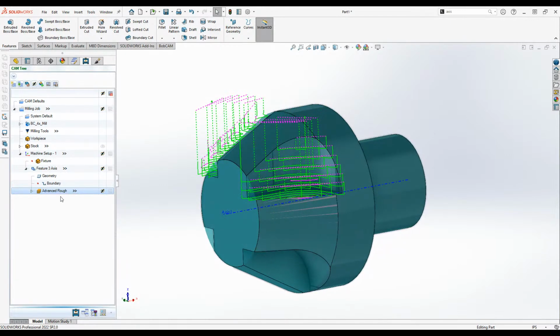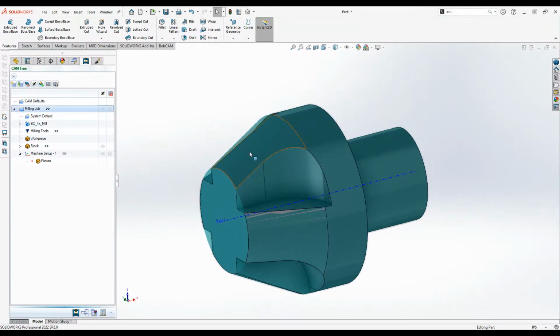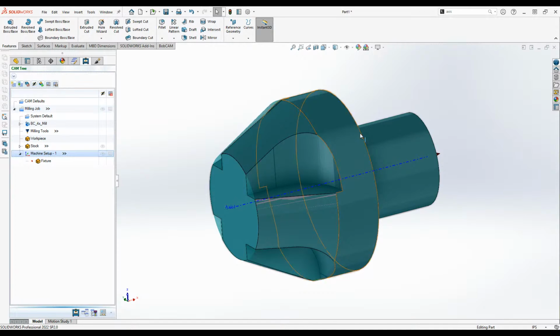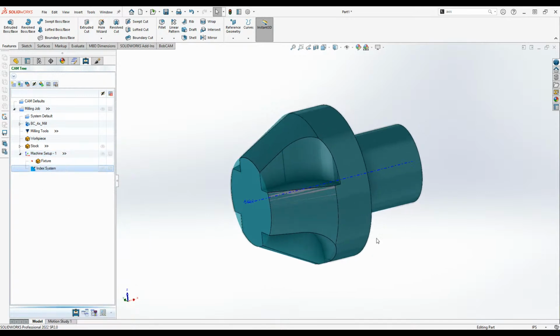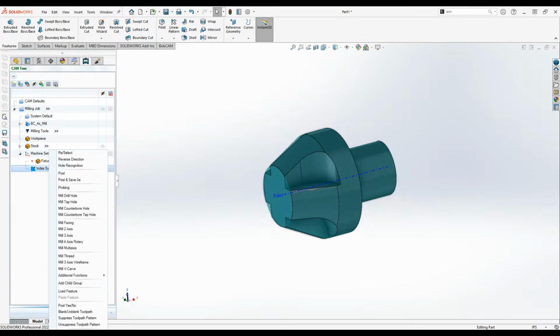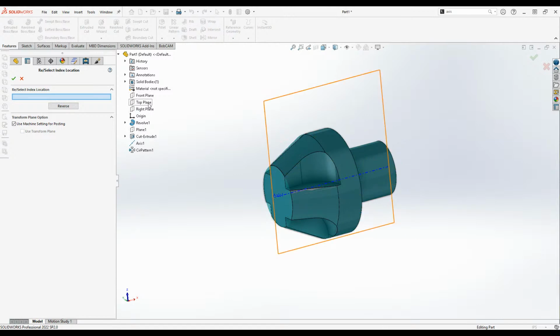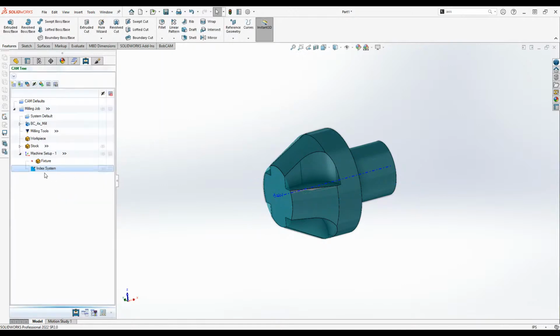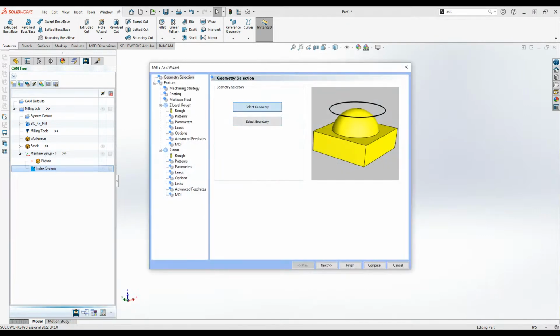Essentially, my big takeaway is that if I'm on a fourth axis and I want to machine on the different faces, even though the Z's align, I'm probably going to load an index system to begin with. That's just going to clock the part. From that index system, what am I going to pick to reference off of? Initially, I may just pick a plane. It may be easy to just pick a plane selection in order to align your Z. From there, we're going to load in a strategy child to that index system.